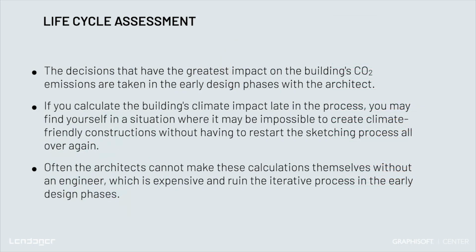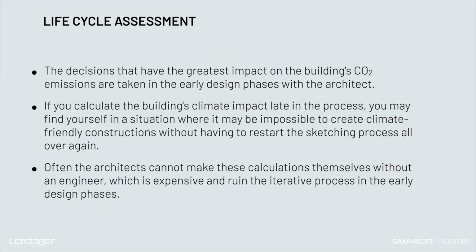The second problem is that you have to do this in the early design phases. The biggest impact on decisions is from the early design phases. And if you only do an LCA at the end of the project, you might figure out that it's too high. Your CO2 footprint is too high. And then you have to redo the sketch process to figure out a new way of designing your building so you have a lower CO2 footprint.